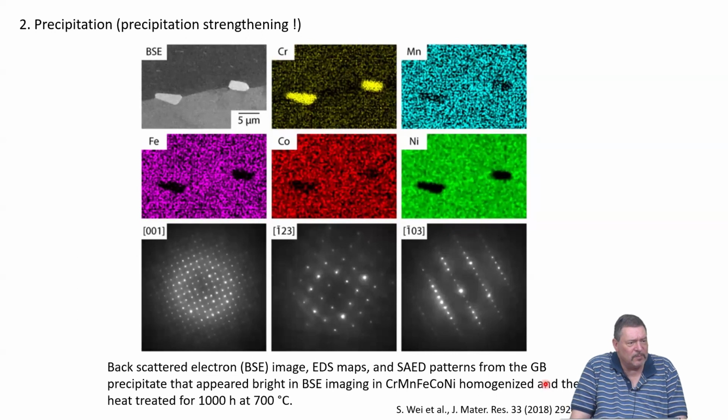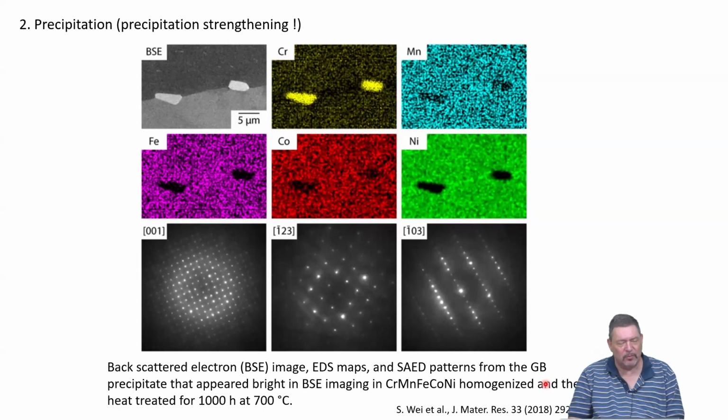This is often very nice because it might impact your mechanical properties in a very good way, because you have additional ways to stop dislocations. The grain boundaries can be pinned. But if you want to make a high entropy alloy really consisting of only a solid solution, then it's not what you want to get. So one needs to be careful. And this is affected mostly by the formation enthalpy of this intermetallic or second phase. So this will overrule temperature times mixing entropy at some point, and then you cannot avoid that these are formed.